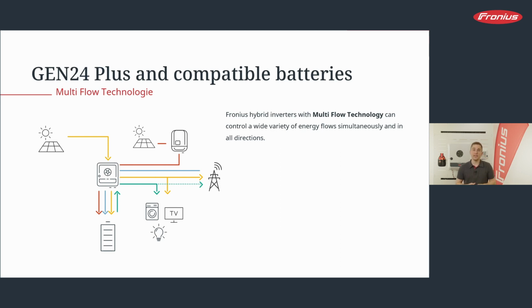So this would mean that all you need to have, for example, is a Fronius smart meter at the feeding point, and then you will get the information of what the alternating AC source is delivering at the moment, and the hybrid inverter will get this information and will process the energy either into the battery system or for other energy management purposes. And the ease of use for this system is that you don't need an active data communication between the third-party inverter and the Fronius inverter.